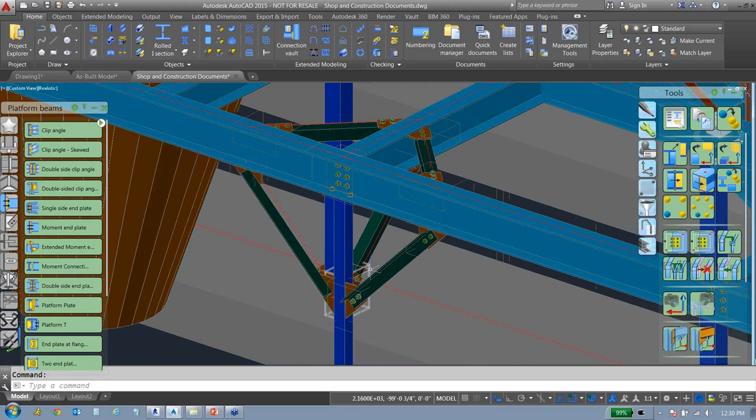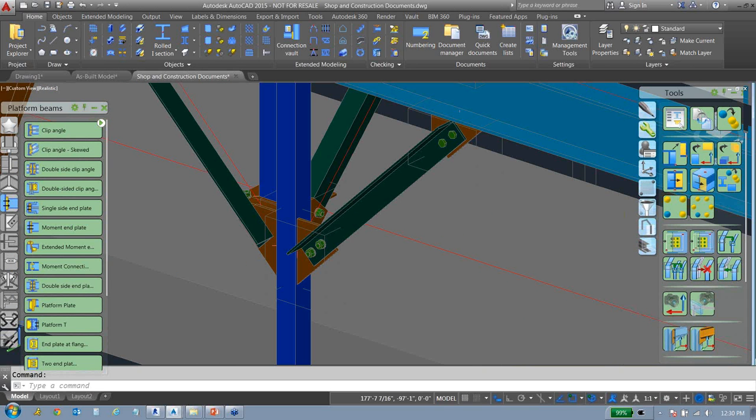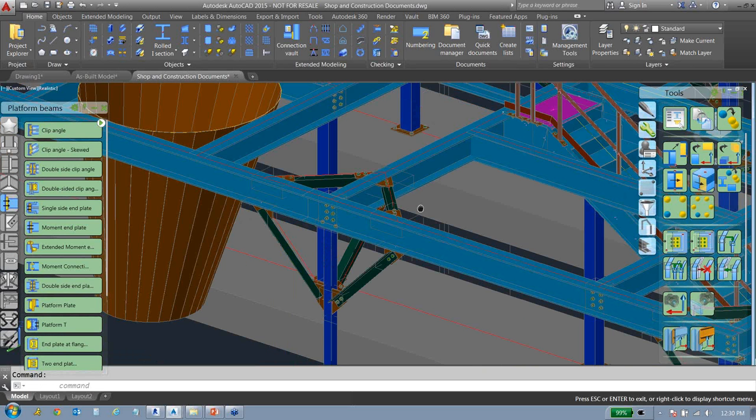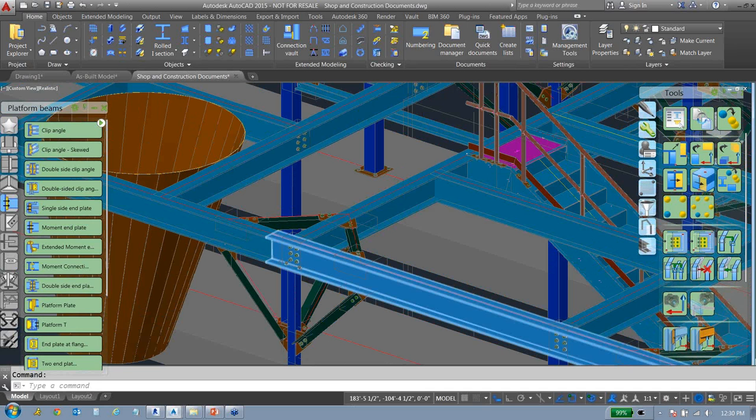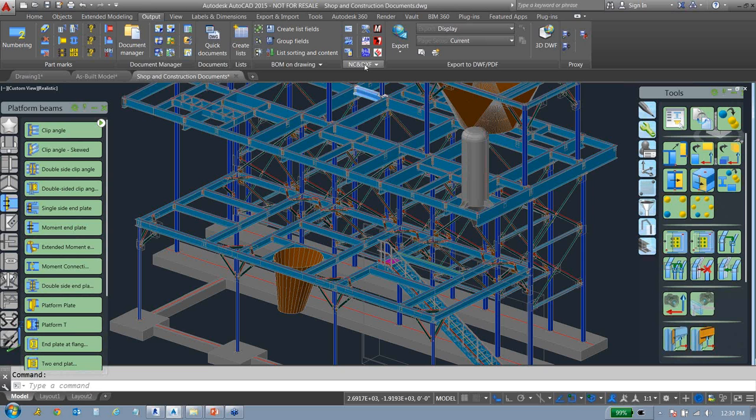Now also, if I need to, I can get the CNC data out of these guys. You can see here on the output tab, we have an NC DXF area here. So two things we use for CNCs is the actual CNC coding as well as a DXF file. So place this guy in here.